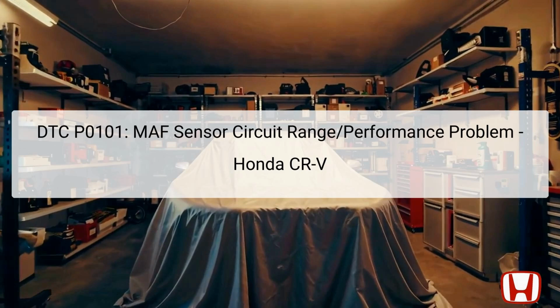The Diagnostic Trouble Code DTC P0101 refers to an issue with the mass airflow MAF sensor in the Honda CR-V, specifically indicating a circuit range or performance problem. This DTC suggests that the signal from the MAF sensor is out of the expected range, which can affect the vehicle's fuel management and engine performance.